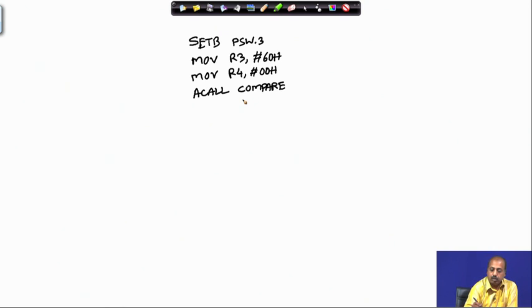Then we clear PSW.3, so that we go back to the previous register bank, and then MOV R0, 08.